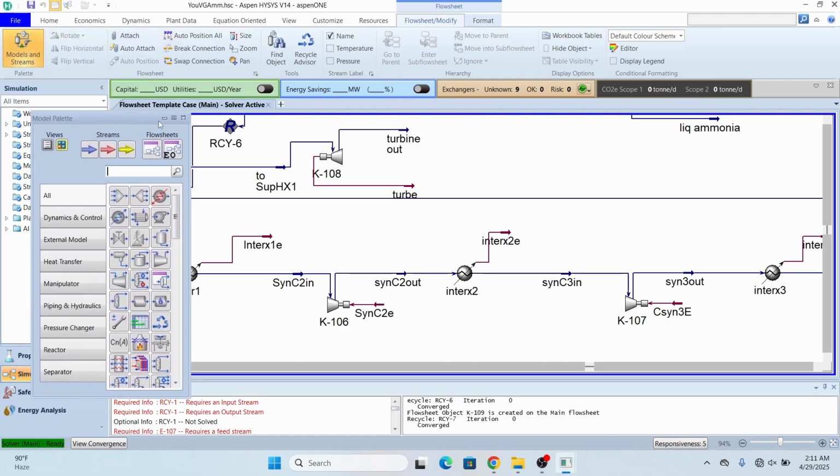We cannot use this energy to run all four compressor shafts, because the energy requirement for all stages is 20,000, and what we are generating with this turbine is only 11,000. For the 9,000 deficit, you can use a motor. If not a motor, you can use a steam generator to produce steam, and then use that steam for running the shafts of the compressors.